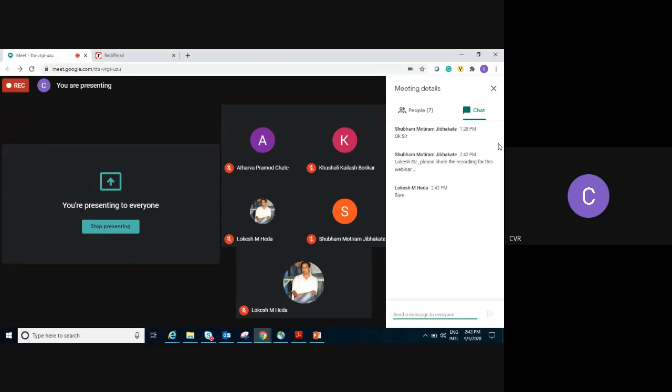You need to really see which kind of application you want to do, what kind of data you want to send, and what range you need. For example, if you want to make a drone to acquire image data, there you need Wi-Fi modules, because you have a large amount of image data, right? And also you need to see the distance. Where you have a smaller amount of data, you could consider some other protocols. So these are the things you always need to consider.